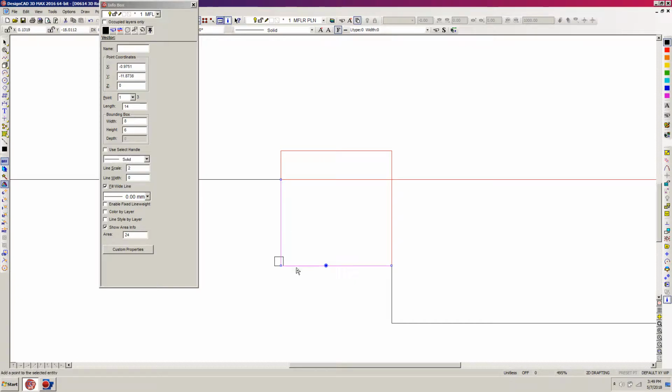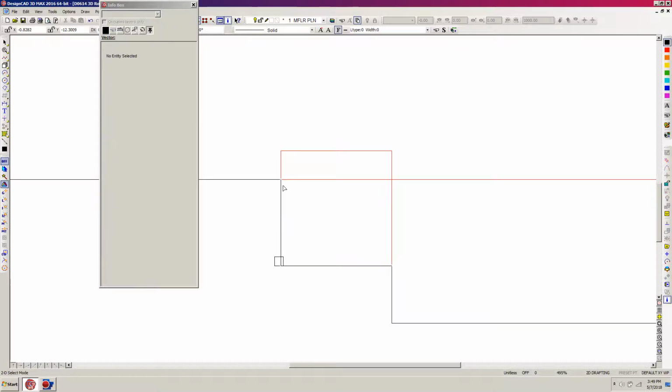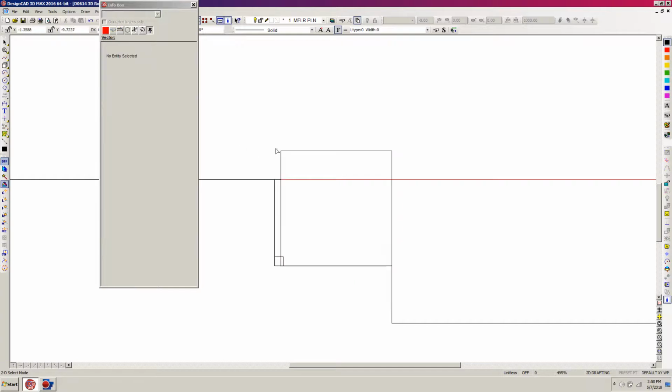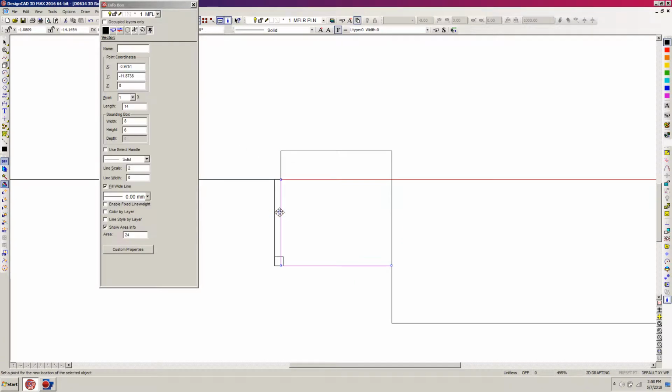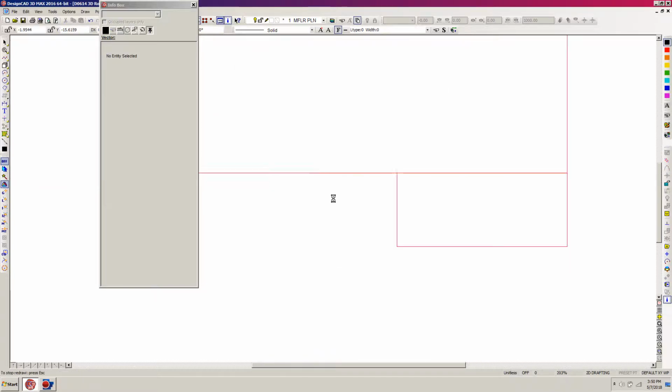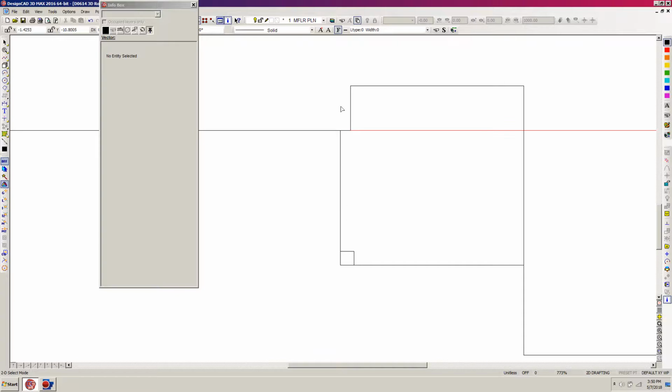And so what I'm going to do is, actually the easiest way to do this is just to go like so. Hit escape. I'm just going to come over 5.5 inches. Hit V for vector, gravity move, minus 5.5 inches. I'm in orthogonal mode. Come to this corner and this corner, and I'm good. Okay, so I can select this point now, and that's the red. I can go ahead and delete that. I'm going to get rid of all of my red, actually. This inside beam line I can get rid of right now. No longer need it.